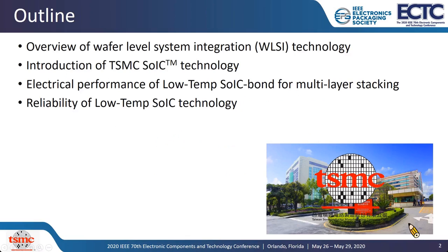In this presentation, I will first provide an overview of wafer-level system integration technology. Then, I will introduce the TSMC SOIC technology by explaining and emphasizing how and why SOIC technology is now playing a key role for 3D heterogeneous integration. I will also provide electrical data which support the development of low-temperature SOIC bond for multi-layer stacking. Lastly, very solid reliability data will be reported to support the newly developed low-temperature SOIC technology.